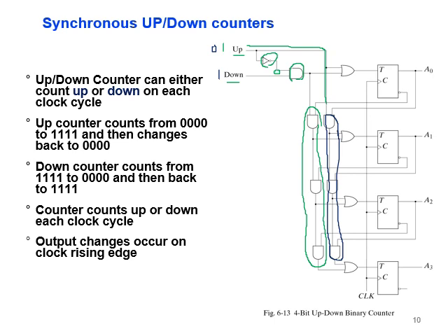Okay, so either we increase in one direction or another direction, either increment or decrement. So just put at the beginning, rather than 3 AND gates, we put in parallel another 3 AND gates and put inputs up and down. 1 for up means the up part will work. 1 for down means the down part will work.